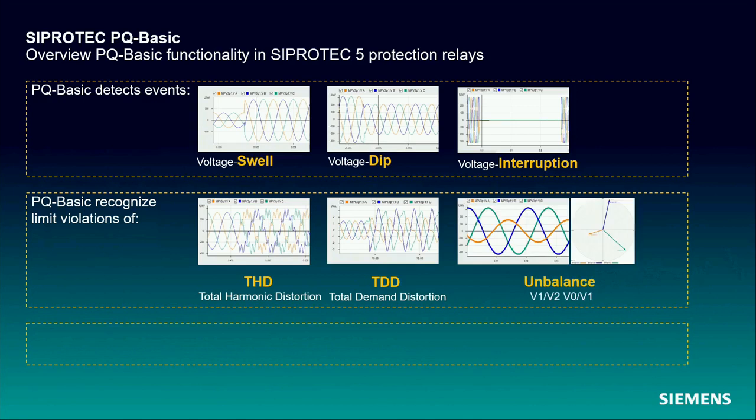The third power quality relevant distortion which needs to be monitored is the unbalance. Here, the evaluation process is slightly different compared to the THD and TDD because voltage unbalances are measured in 3 seconds average values. These average values will be stored and evaluated over a so-called observation period. At the end of that observation time range, all 3 seconds values come under consideration, if and how many of them exceed the upper limit for unbalance.